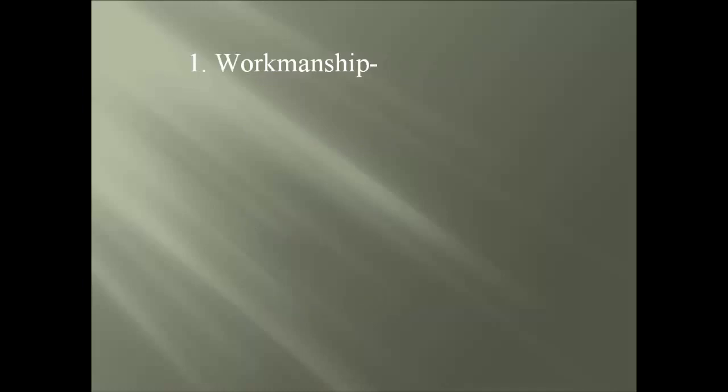We start with the first topic, workmanship. The AWS D1.4 code scope shall apply to the following: the welding of reinforcing steel to reinforcing steel, and reinforcing steel to structural steel. The D1.4 code shall be used in combination with the building codes and project specifications. A quick tip: any impact testing requirements of welding reinforcing bars are not included in the D1.4 code.